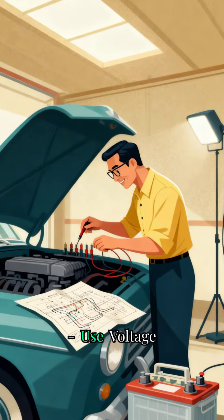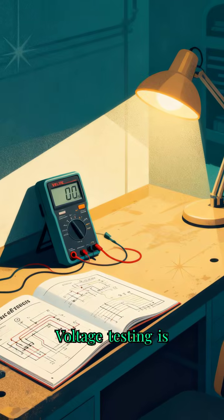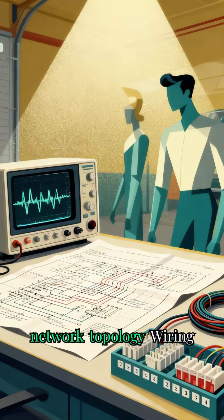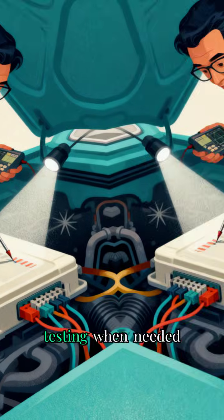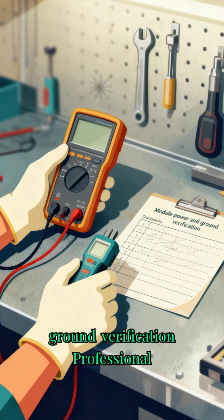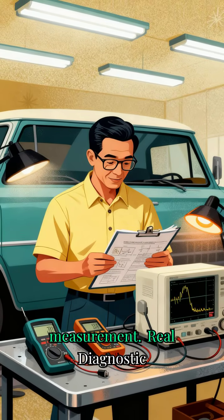Step 6. Use voltage with other tests. Voltage testing is an excellent first step, but it should be combined with scan tool network topology, wiring diagram analysis, oscilloscope testing when needed, and module power and ground verification. Professional technicians rarely rely on a single measurement.